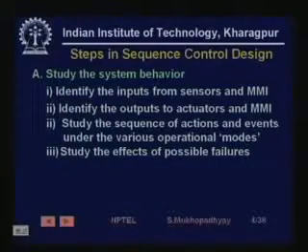Then one thing that must be very clearly remembered is that when you are developing an industrial automation program, one not only has to design for normal behavior, but one must to some extent at least take into account the possible failures that can occur. Otherwise, a system that behaves well under normal behavior can behave in a very nasty manner if some simple element of the system like a sensor fails.